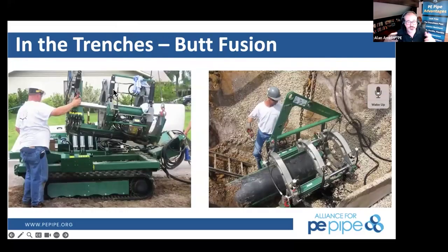So for larger pipe, this becomes a much bigger problem. Obviously, with larger pipe, the logistics of being able to get all of that together in those areas becomes more challenging as we see it. So for the haunch area, for a smaller diameter pipe, a lot of things will settle right down into that area. The workers themselves can go through and support that. The compaction around the edges obviously is a long-term thing for any type of compaction, especially up against manhole edges or anything of that nature.